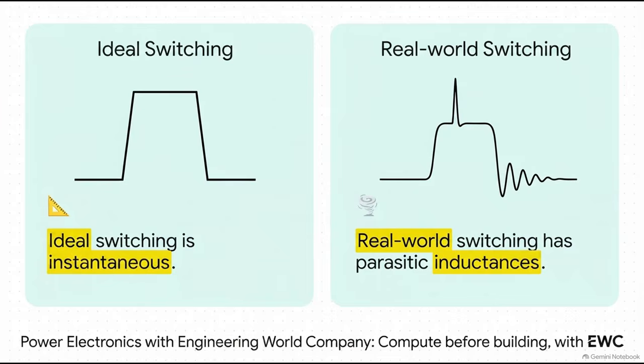And honestly, this brilliantly illustrates the massive gap between ideal switching and real-world physics. In a textbook, switching is instant, but in reality, as literally anyone who's ever debugged a smoking prototype knows all too well, you don't just have clean 13 nanosecond overlaps. You've also got parasitic capacitances, PCB trace inductances, ringing, and overshoot ripples that complicate the waveform even further.